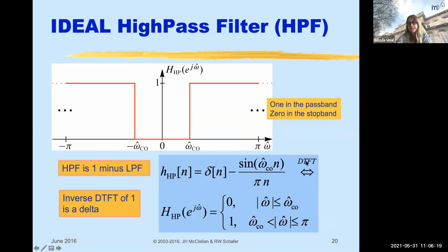It's time domain representation, and its discrete time Fourier transform is really exactly this one. Yes, actually, because we are using 1 minus low pass filter, and inverse discrete time Fourier transform of 1 is a delta. That's why we had this. Okay, so this is a pair then, right? What I'm showing here is a time and frequency domain pair, Fourier transform pair.